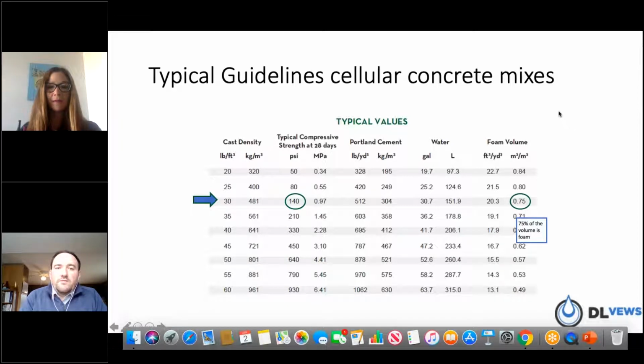And I would say if it is stagnant water, it's quite possible you can force that water out by head pressure, meaning as soon as that grout starts to fill that annular space, it'll start to displace whatever residual water is in there. And as you know, Cassie, and most of the folks on this call have had some experience with it, you can usually displace that water out of your ports at the bottom end of your bulkheads.